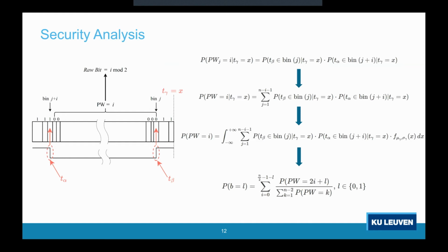So, as you remember from 3 slides ago, the time-to-digital converter and the pulse width encoder map a relative position of the edges alpha and beta to the edge gamma into a random bit. So, at the sampling moment determined by the edge gamma, the bins in the delay line should contain a string of at least 1 bit with value 0, encircled by the bins with strings of 1s, as you see in this picture.